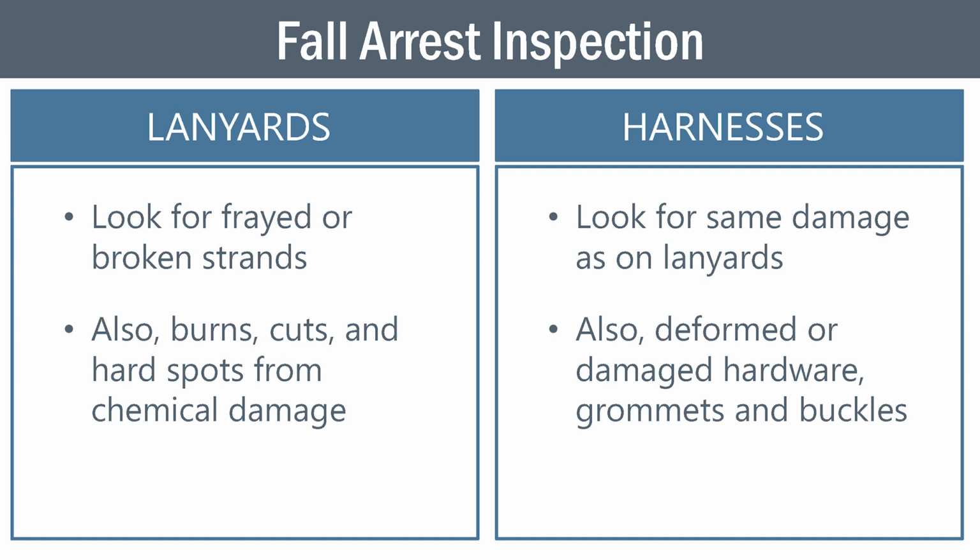Because you always inspect it before you use it. Notice that. If you've got it hanging up in the shop, you're not going to inspect it every day unless you want to. All right, but what does OSHA want you to do at a minimum? Before you use it. Now, what's really good about the annual inspection is you're documenting that somebody has gone back and making sure your fall protection systems are working, as part of it inspecting your harnesses, your lanyards, things of this nature. That's great. That's an attaboy type deal. Okay, so y'all doing good.